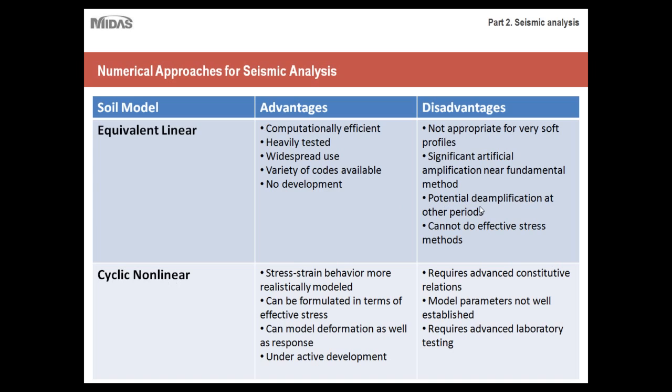Just before I continue, there's potential de-amplification at other periods, so that's just another way to say that there are certain assumptions made as far as your time history graph. And then it can't do effective stress methods, so it can't take undrained conditions into account.